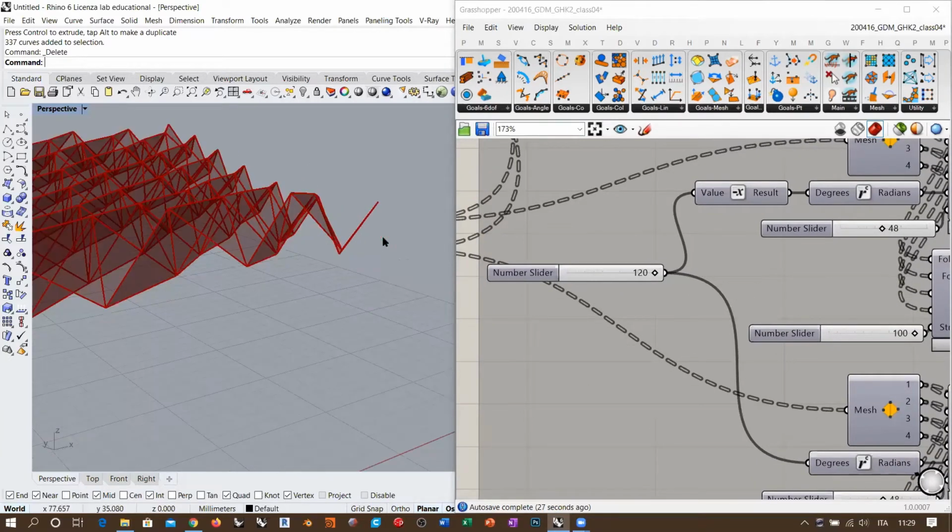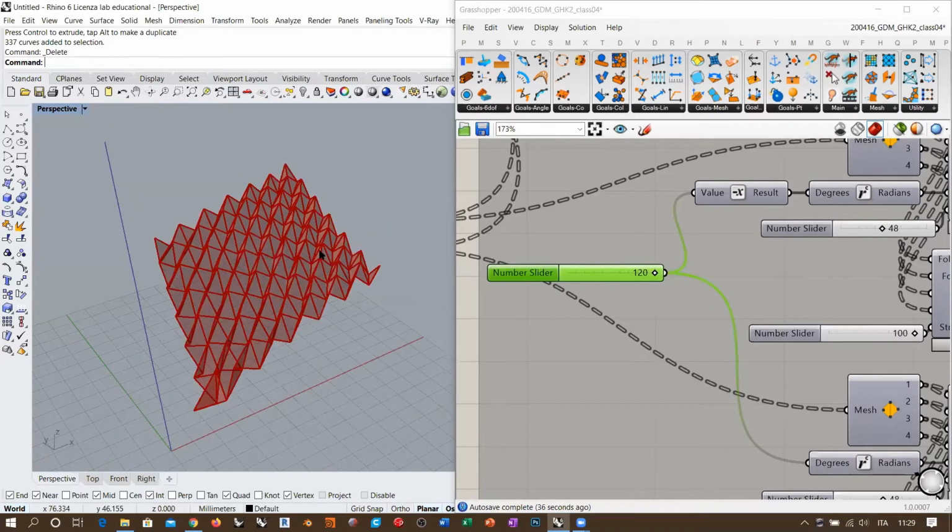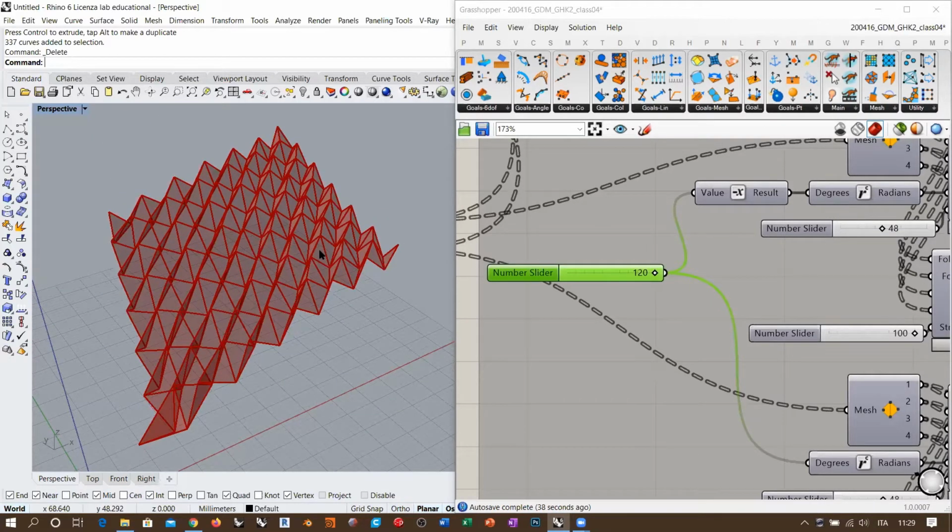You see that if you want this object to pack completely, you must reach 180 degrees. I do not recommend you do this because in the real world, two objects cannot coexist in the same exact location in space. So it is a mathematical or a totally hypothetical behavior, the one that uses a rest angle of 180 degrees.